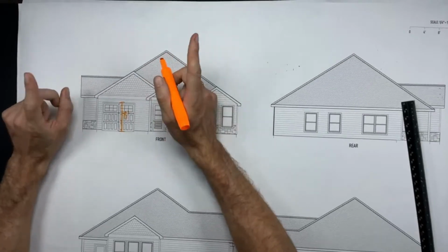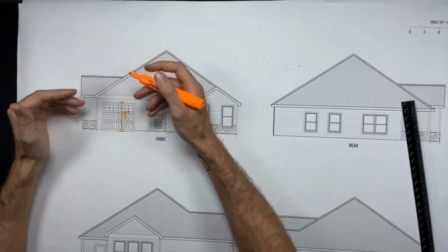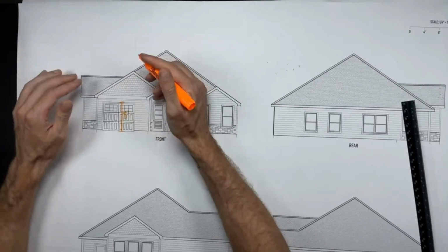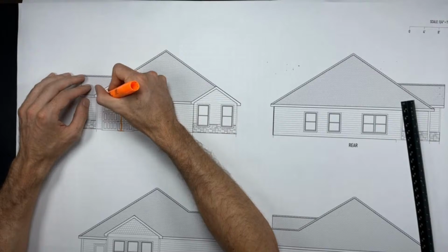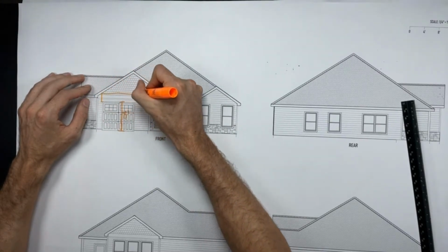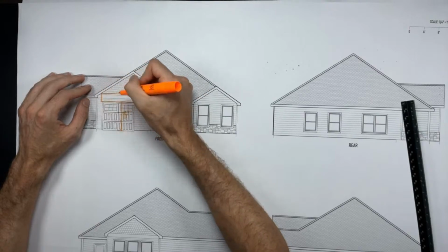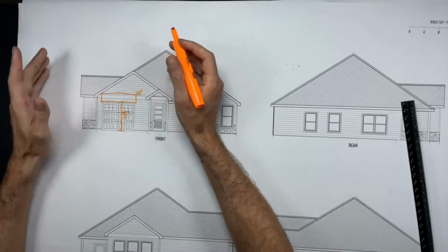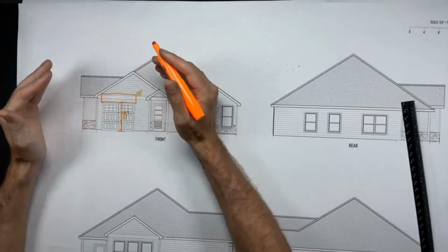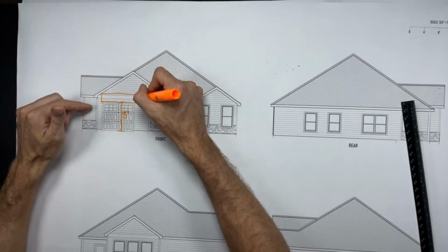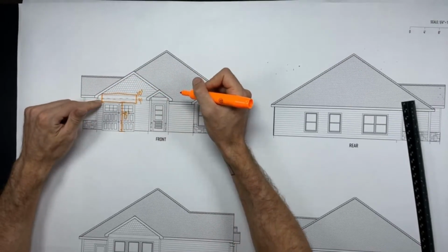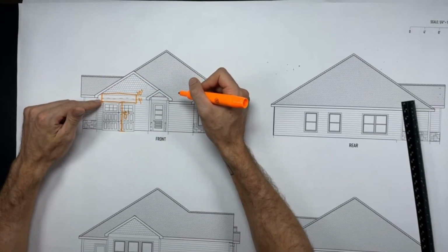Architects or designers will sometimes say, yeah, my roof is designed to start here. It wouldn't matter here because I have a gable wall, I could push the beam up. But if I didn't, then my header exists about right here. So if my header needs to be 2 feet tall, the bottom of the header needs to be at 8 feet. Guess what that means? The top of the header is at 10 feet. Some designers will design houses and say, oh yeah, the plate height was 9 feet for the roof to start at, like down here. And then they go to build this thing and the framers are like, dude, what are we going to do?